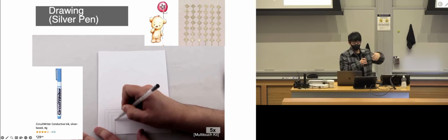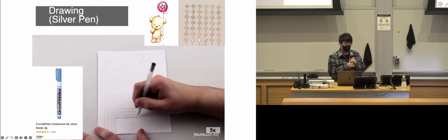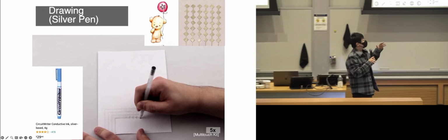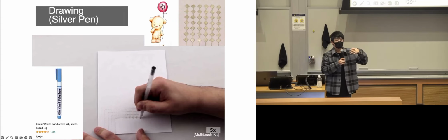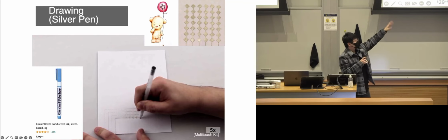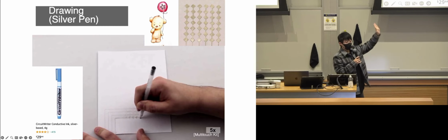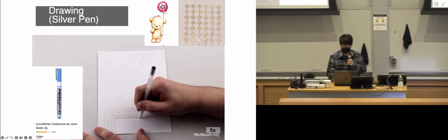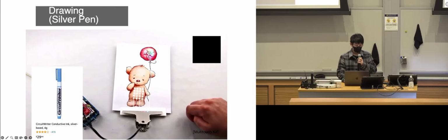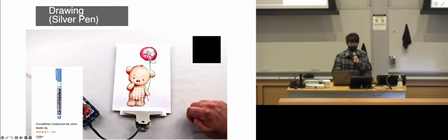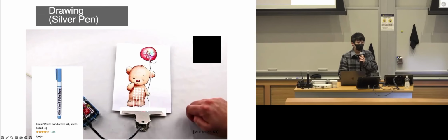As long as you can draw, you should be able to draw out the circuits essentially. And by making different shapes of the components, you can also build more complex circuits, for example, capacitive touch screens. If you just draw them in this layout, and then have 2 layers of them attached on top, the entire circuit is just drawn, and you can use it as a capacitive touchpad.